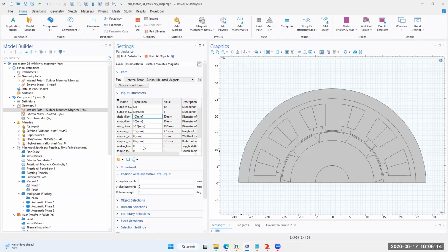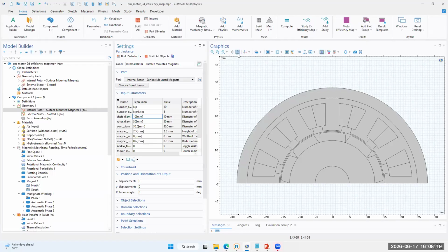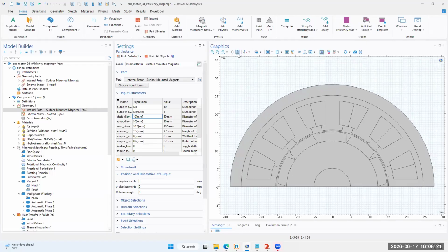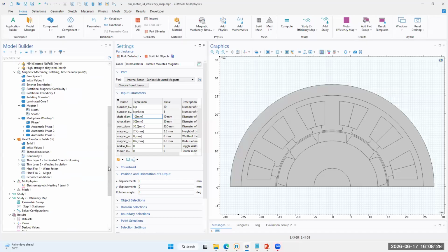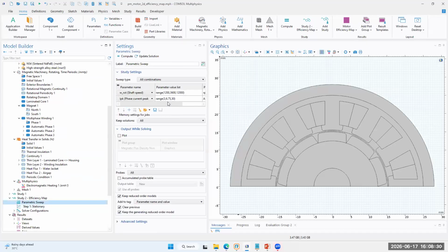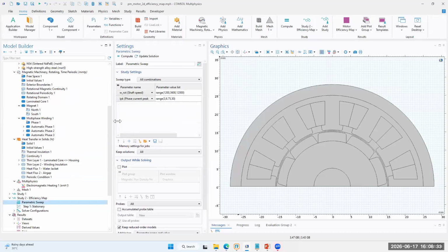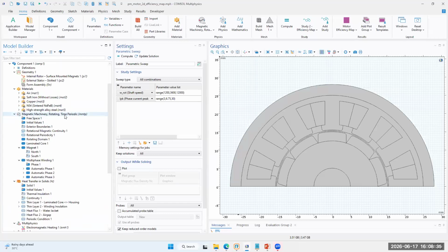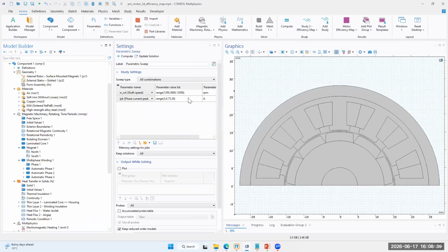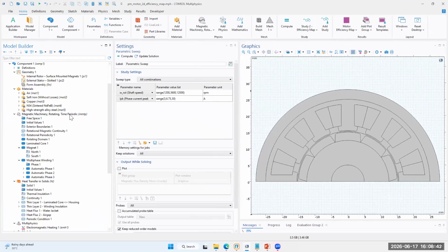When multiple parameters exist, you can use that aspect as well to derive which parameter will highly influence your motor performance. But in general, a parametric sweep analysis is as done here. When you are doing a parametric sweep, if it is going to be large and extensive, you would choose this time periodic approach, which will help you do parametric analysis in a faster duration.